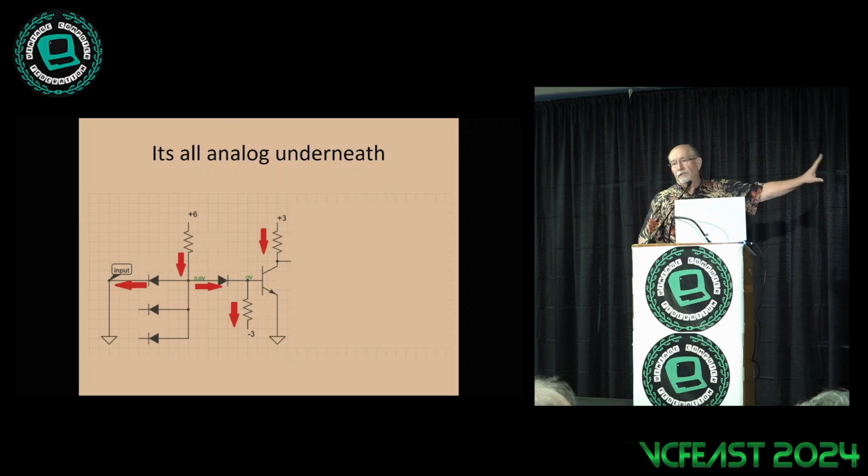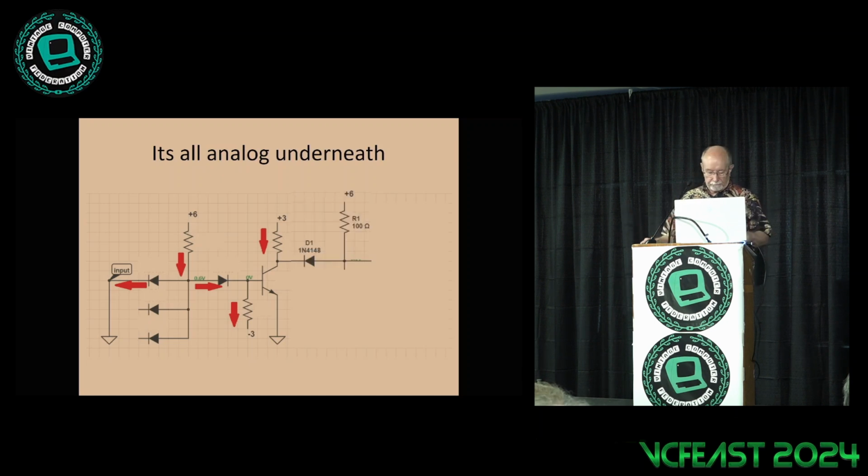So here's one of those standard diode transistor logic gates with an input down at 0, so it's tied to ground. That means the junctions pull down, and the transistor's cut off. The pull-up resistor on the top right is delivering +3 volts out. That's what we expected to see, wasn't it?